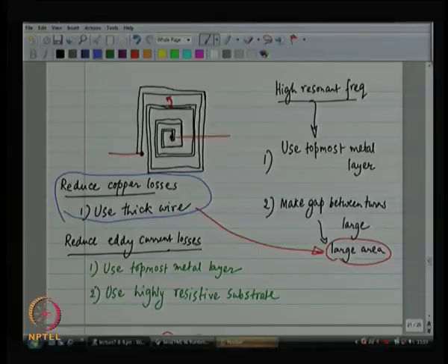Okay. So, when you work with your inductor, when you design your inductor, please make sure that you have worried about skin depth. Please make sure that you have done some computations to figure out exactly how much the depth of your skin is, and then what is the thickness of the metal that the foundry is providing. So, only after these computations sign off on your design. Do not ignore skin depth.